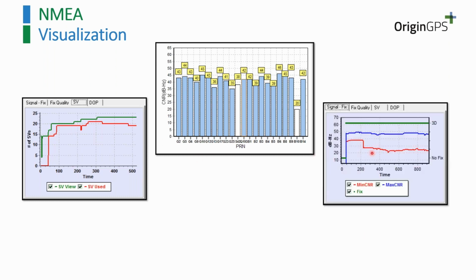Another part is about handling the NMEA and making not just read and visualization, but also taking the NMEA and making algorithms. For example, here it's an algorithm of max hold and minimum hold. So I can know what the signal quality is in total, not looking at every satellite specifically, like in this picture, but taking all the values together and seeing what is the minimum and maximum.